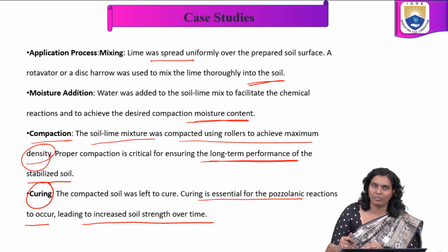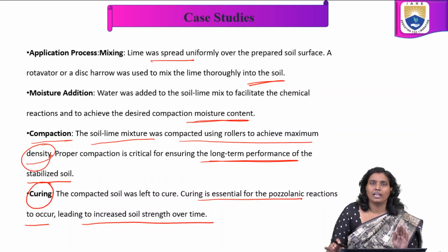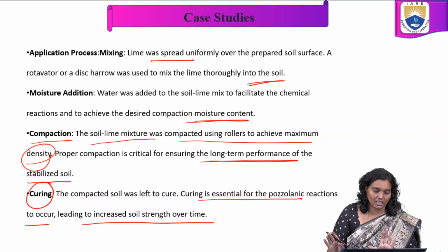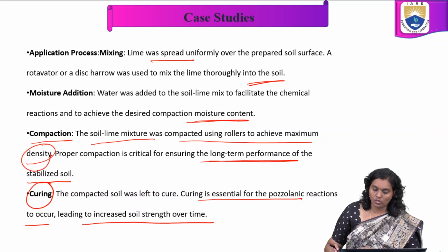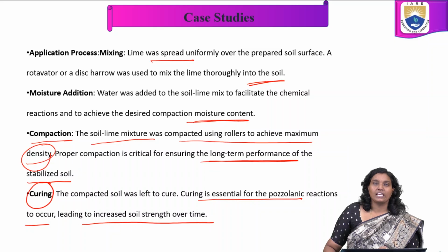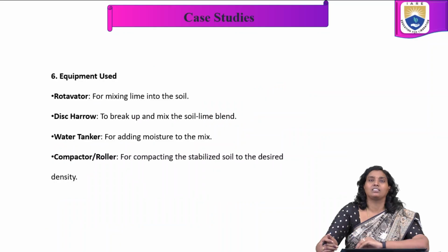Then the application process: mixing is done and the lime is uniformly spread. Any moisture addition required is done, and also the compaction. It is important for getting the stabilization of the soil. Because of the pozzolanic reactions, the curing step also leads to increased soil strength over time.